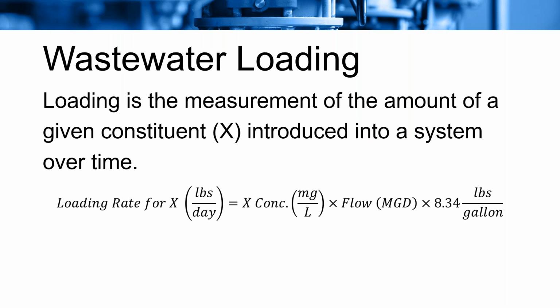Okay, so the first topic we're going to talk about is wastewater loading. Loading is the measurement of the amount of a given constituent, which I like to just designate as X, introduced to a system over time. So the most basic way to represent that is just the loading rate for that X compound, and it's going to be pounds of it per day.